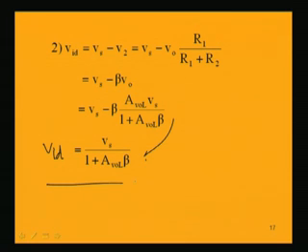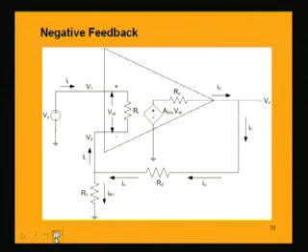Now, in this exact circuit using the practical OpAmp consideration, one thing to notice here is that the feedback which is there is a negative feedback, meaning to the applied voltage Vs, the feedback voltage is adding up in a negative way. What is the feedback voltage?